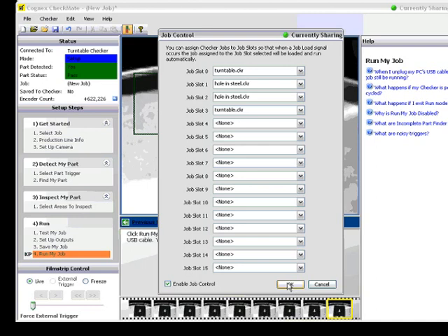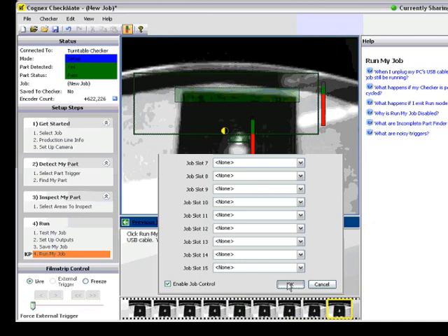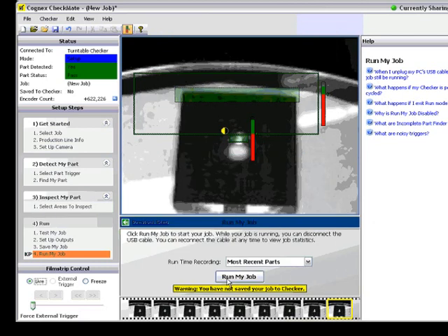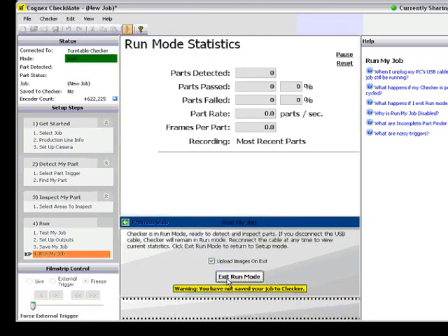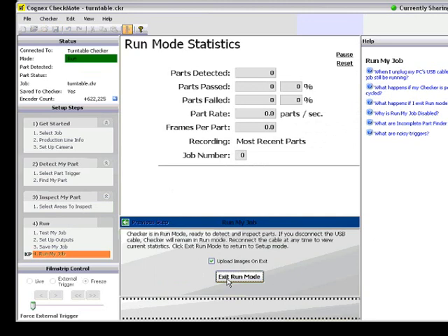Now I have another plate that goes on my turntable here. And what we're going to do is throw this in the run, because the only way you can change job files is in run mode. I'm going to punch my little push button on there that loads the job file. It's 4 bits, 0 through 4, and a 5th bit needs to be toggled on the I/O module to change the jobs. That can be done with a rotary switch, or a thumb wheel, or a PLC.